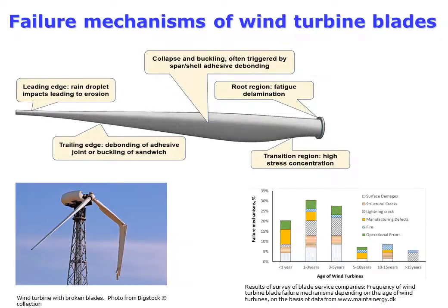How, and why, do the wind turbine blades fail? Wind turbine blades are subject to complex environmental and mechanical loading during their service time. But they can also fail due to extraordinary events, like transportation damage, lightning strikes, bird impact. Several regions of blades are especially susceptible to degradation during service time. Leading edges of blades are subject to rain and hail erosion. Transitional regions, for instance, ply drop, area of transition from cylinder to aerofoil, tend to show delamination of composites. Adhesive joints can debond, and it can trigger buckling of structure. This failure mechanism can be observed in trailing edge or at web to spar joint.